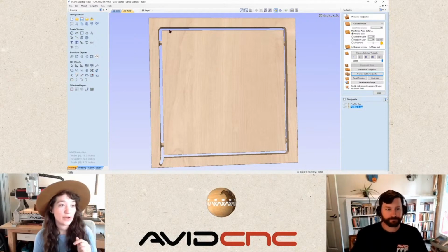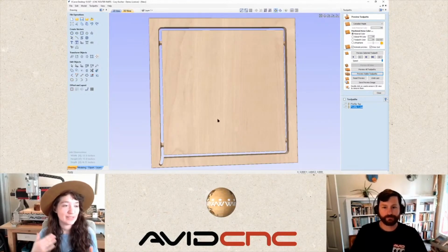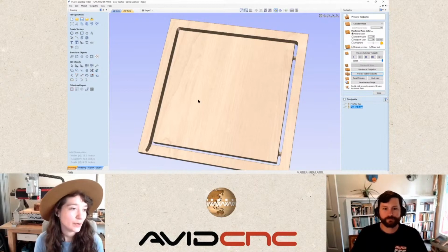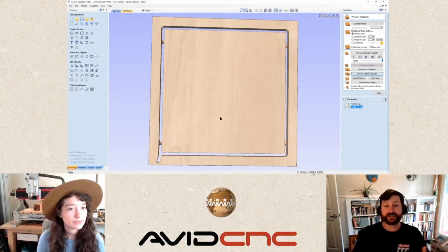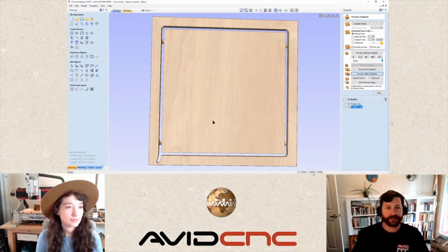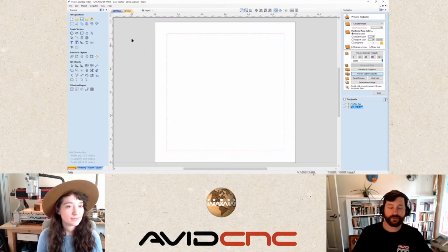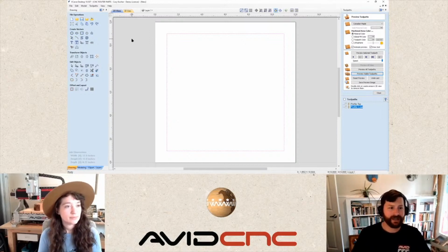Right, and also note that this is a 10 by 10 inch square, so we're able to get up to that set predicted feed rate that we entered for this particular toolpath. Yeah, if we would have programmed this at 300 or 600 inches per minute, that would be an unachievable feed rate. And we can definitely achieve that 100 or 200 with one of our Pro Series machines. So let's hop into the next type of toolpath, Sami, which is a pocket, or in this instance, we're going to use kind of like a dado as an example.